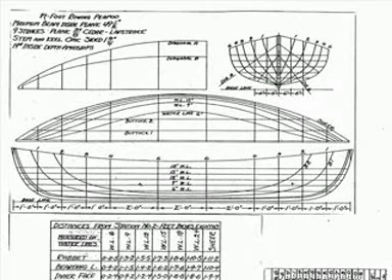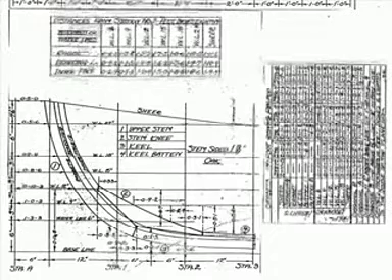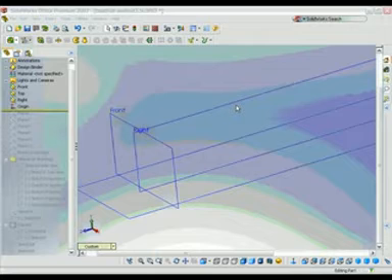Traditionally, boat hulls are built using a number of cross-sections that are first calculated on a drawing, using values to determine the cross-section of each placement as it goes from the aft to the stern. In this case, I have a drawing that describes this, but I don't have any 2D geometry. I want to quickly visualize this boat hull design, so I'm going to take this drawing and exploit it by using our sketch picture feature to paste this drawing into our 3D part and use it as reference as I build my freeform against it.